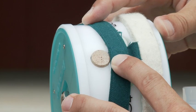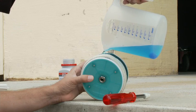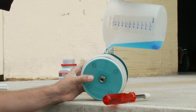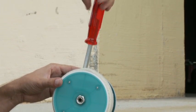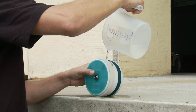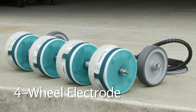The felt hoops and the felt hoop connector should be saturated with water to ensure a low resistivity contact before measuring. The electrode should be filled as completely as possible with a minimum of air in the compartment. And in order to ensure that the solution remains saturated, add an additional teaspoonful of copper sulfate crystals into the electrode. Close the copper sulfate compartment by using the Allen screwdriver included. Then open the water compartment and fill with water. For the 4-wheel electrode, each of the wheels should be prepared in the same way.